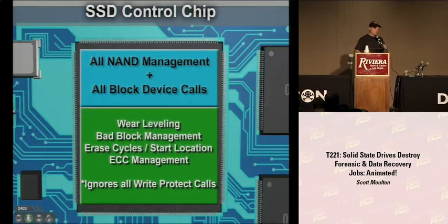Maybe some people can reverse engineer some chips and make some changes to the code, but at this point, that may affect us and cause us some major problems. The longer it's plugged in, and you leave it overnight and come back tomorrow, it may be done with its garbage collection routine and erased more data than you thought it would during that time span, even though it's fairly quick at erasing because it has its own processor. I just want to make sure that's clear to people dealing with forensics.